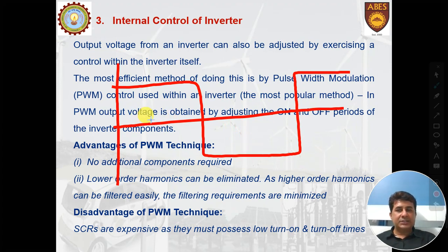The more the waveform is away from the sinusoidal one, the more harmonics there will be. Harmonics are there in this kind of waveform because this waveform is totally different from the sinusoidal waveform. When you perform the Fourier analysis of any waveform, you get to know how much harmonic content it contains, that is, how much this waveform differs from a sinusoidal waveform.